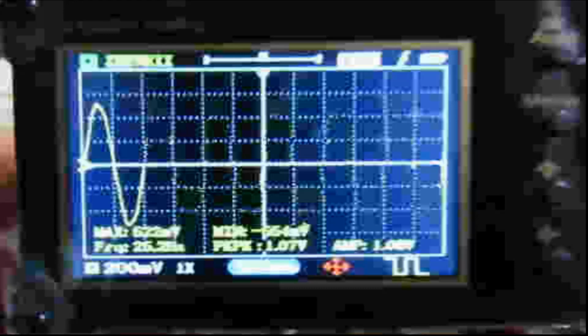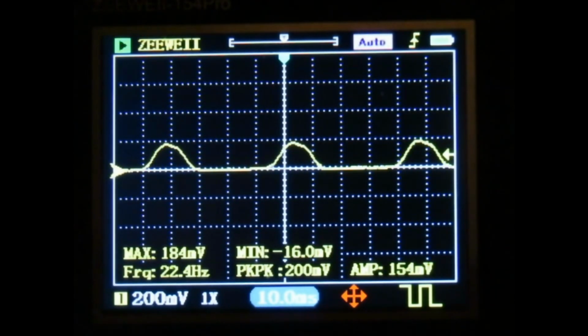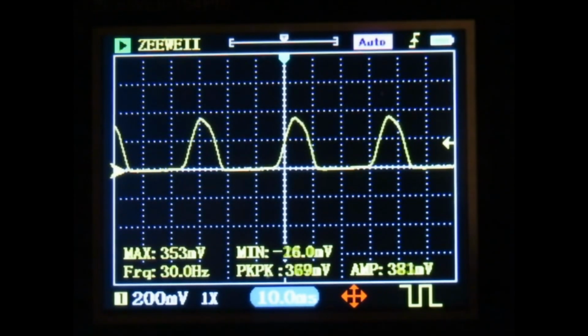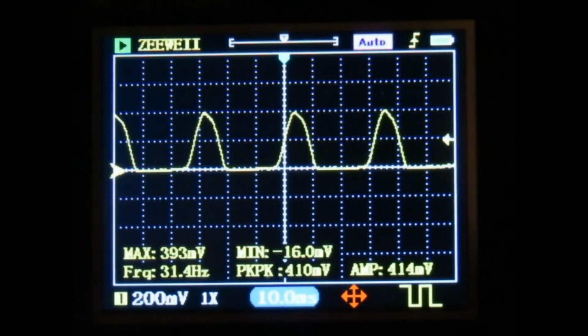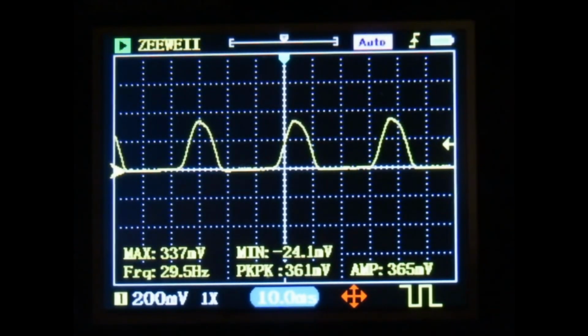If starting at the 0 line, it looks like this. But when you install a diode, you get a voltage in one direction, but not the other. It looks like this. Notice on the forward biased AC cycle, you get current flow, the arc above the center line, but not on the negative biased AC cycle. You only get the center line or 0 line. So you're missing the negative direction.